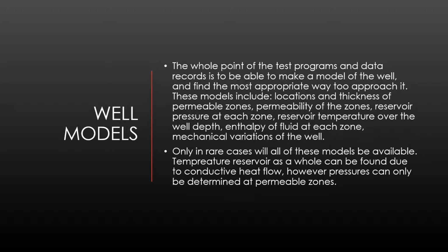Well models. I've been using this word throughout this whole presentation, but the whole point of the test programs and data records is to be able to make a model of the well and find the most appropriate way to approach it. These models include locations and thicknesses of permeable zones, permeability of the zones, reservoir pressure at each zone, reservoir temperature over the well depth, enthalpy of fluid at each zone, and mechanical variations of the well.